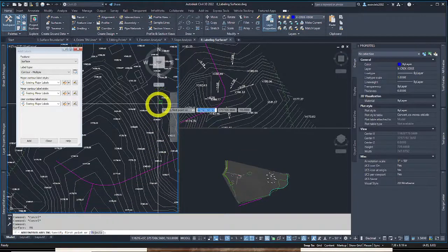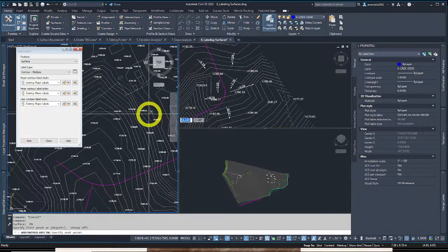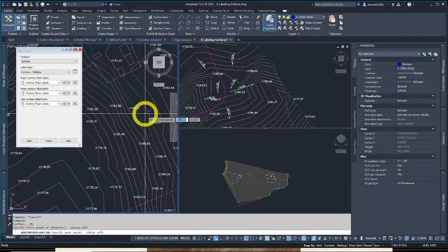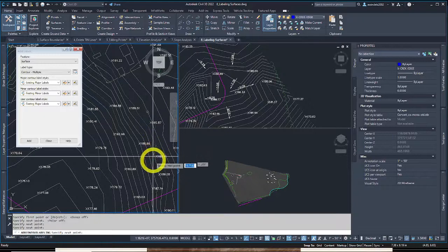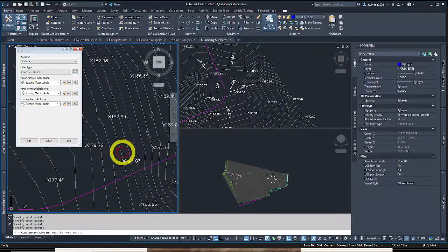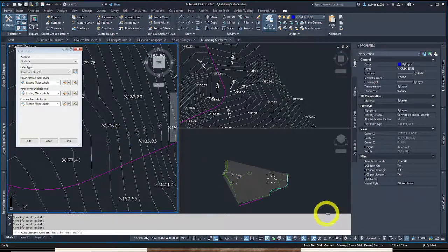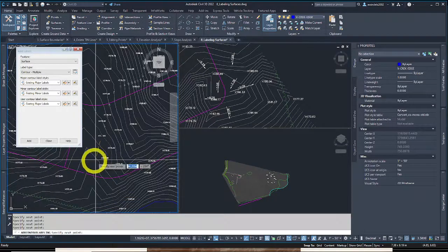And you can get really interesting. I'm going to turn my OSnap off. That's going to be a pain a lot of times with this stuff. We'll go pick where we want. And I'm going to turn off my ortho and polar tracking so that I can go at any angle I want, which with these is handy. And you'll see why in a second. I'm going to zigzag through these so they don't overlap exactly where I want. Keep picking. They're small enough right now at this 1 inch equals 50 foot scale that they all can fit, and the style is small enough where they do okay.